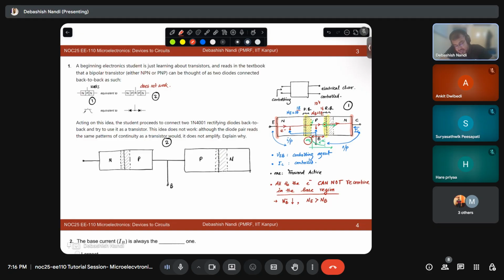So the way the PN junctions create PN junction diodes, these metal semiconductor junctions create one of two types of things. Either it will create a resistance, which we call an ohmic contact, or it can be Schottky.